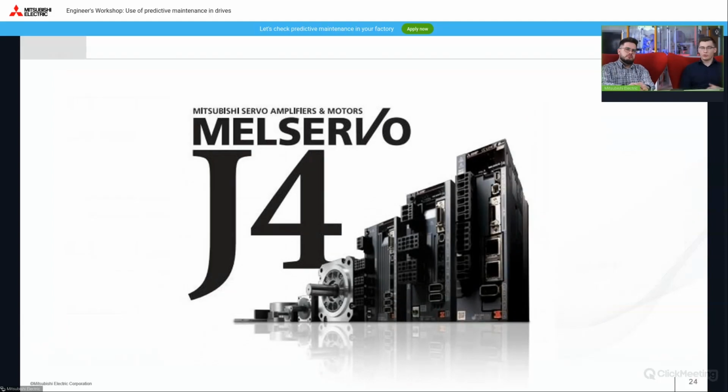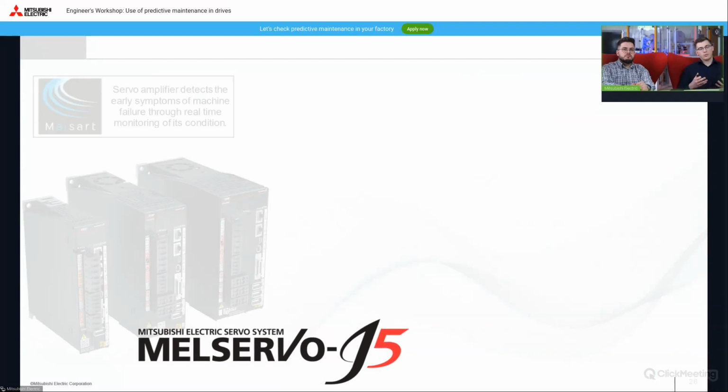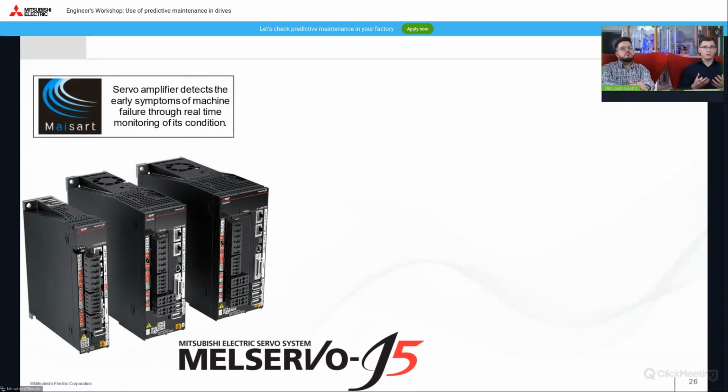In J4, the previous series, we already had a function which allowed us to collect data about the movement resistance and so on, but not as developed. And let's go back to the present right now, because J5, the newest series, has Maisart. That is to say, as standard, without additional fees or licenses, the servo amplifiers are equipped with algorithms that can be used for prediction. And what do these algorithms allow us to do?